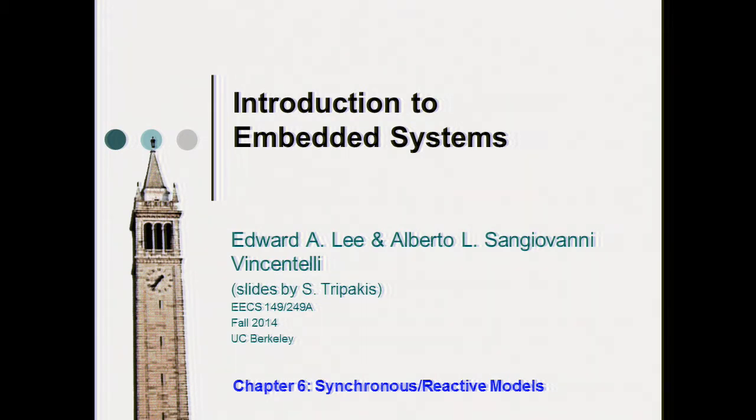So if you look at circuit design, and this approach by the French community comes from the hardware design side. In circuit design in the 70s, everybody was designing asynchronous circuits, right? And so the problems were about the fact that you had race conditions, so the actual results, the output of what you design, depends on the data.